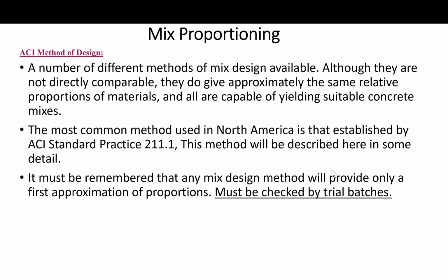It must be remembered, however, that any mix design method will provide only a first approximation of proportions. So these must be checked by trial batches, as I mentioned, in the laboratory or in the field, and then adjusted as necessary to produce the desired concrete characteristics.